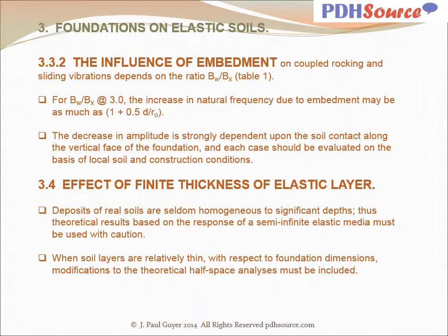The influence of embedment on coupled rocking and sliding vibrations depends on the ratio B_W divided by B_X, refer to Table 1. For B_W divided by B_X at 3.0, the increase in natural frequency due to embedment may be as much as 1 plus 0.5 times d divided by r_o. The decrease in amplitude is strongly dependent upon the soil contact along the vertical face of the foundation, and each case should be evaluated on the basis of local soil and construction conditions.